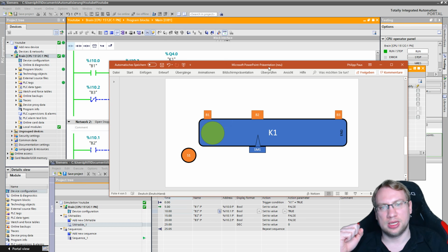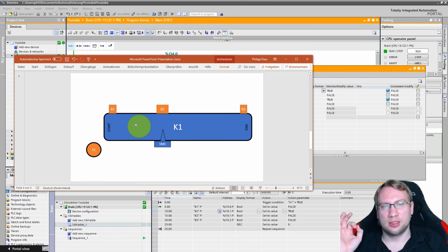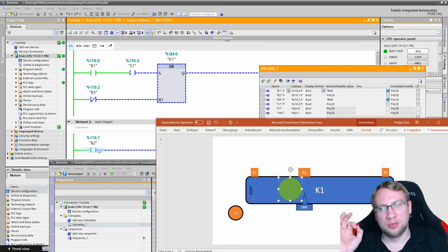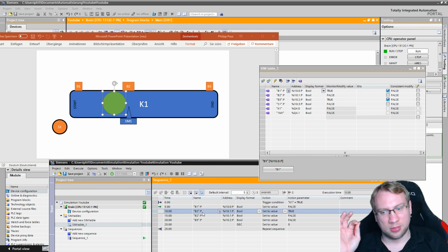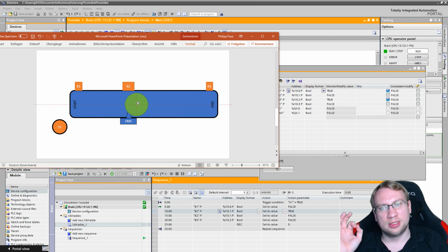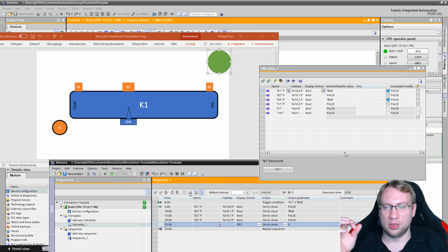What I need to do is press S1. I'll press it in a moment. Then the conveyor will turn on. 5 seconds, right? B2 will activate because it's here in our sequence in the second place. Then a couple of seconds later, B2 will deactivate because the component moves on. And even a couple more seconds later, B3 will send a logic 1 signal because there's a piece. And then B3 won't send 1 anymore, which I don't have in here, which I will add now because someone takes off the piece again.